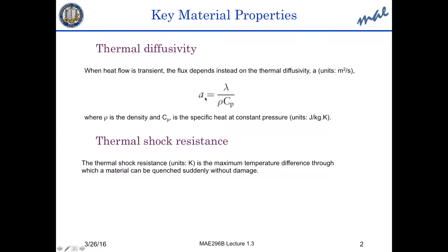So the diffusivity a is the ratio of lambda over rho Cp. So if I take lambda divided by a, then we would get rho times Cp. So it turned out to be that rho times Cp is dependent on the density of the atoms of the material. And therefore, for most materials, the product of rho times Cp is very similar. The only exception, as we will see, is micro-engineered materials such as foams, for example.